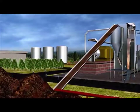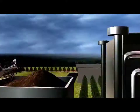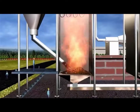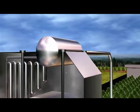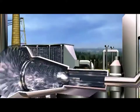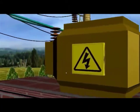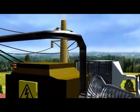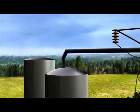The soya husk is transported over a conveyor belt into the bunker of the cogeneration plant and is burnt in the furnace. The heat is utilized to generate high-pressure steam. The steam is fed to the back-pressure turbine, which generates electricity for the production plant. The expanded steam of 12 bars and 6 bars gauge is used in the production processes as a heating medium.